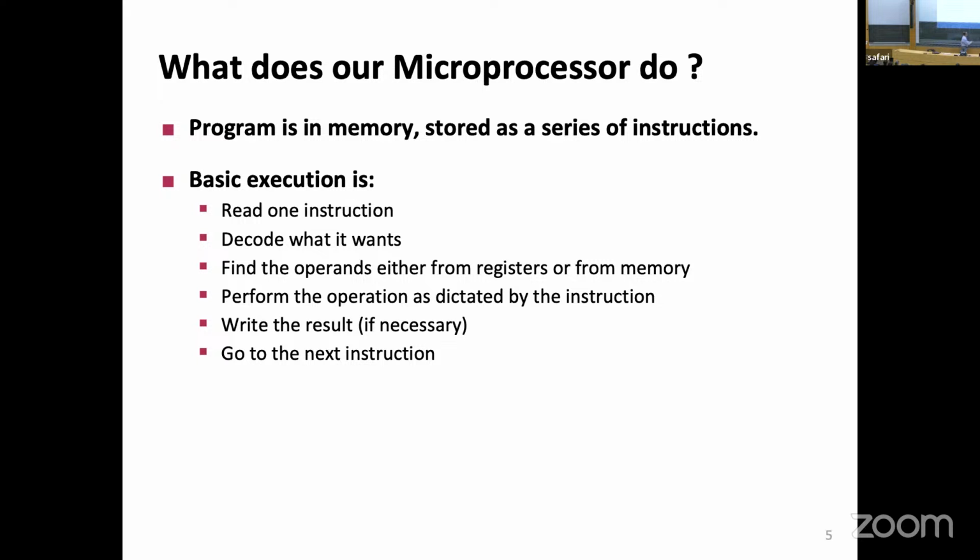I produced the result, 32 bits so that we are clear. Then the result came back here and we wrote it back to the register file. We also had to make sure that we are writing to the register file. There is a control signal called RegWrite. Okay, we did it. We ran our instruction and wrote the result back.